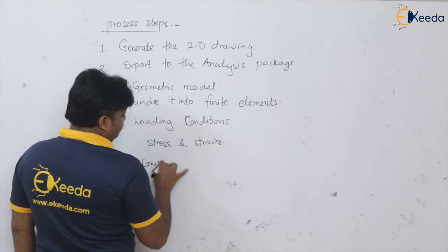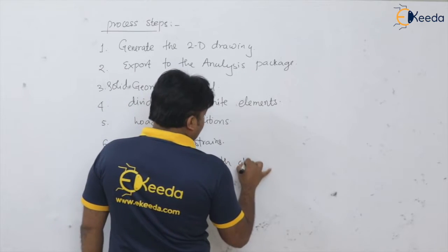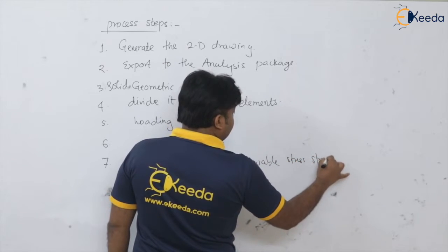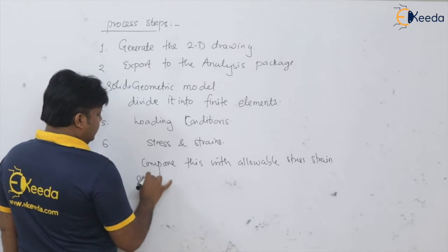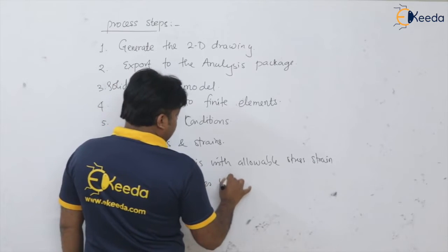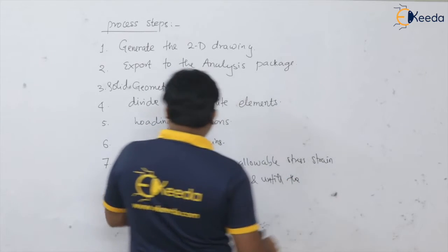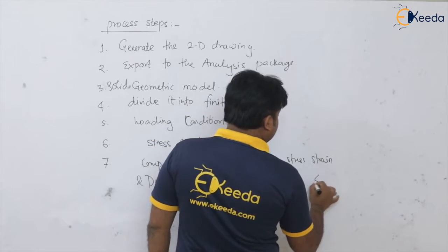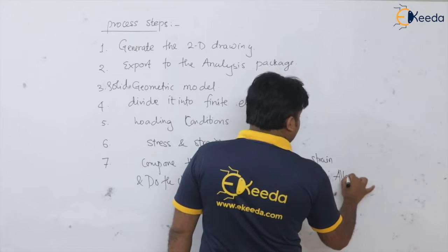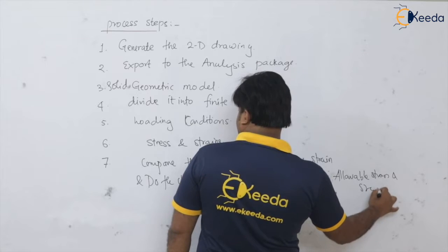So compare these stress and strains with allowable stress and strain and do the changes if required, actually, until the stresses and strains are less than or equal to the allowable stress and strains.